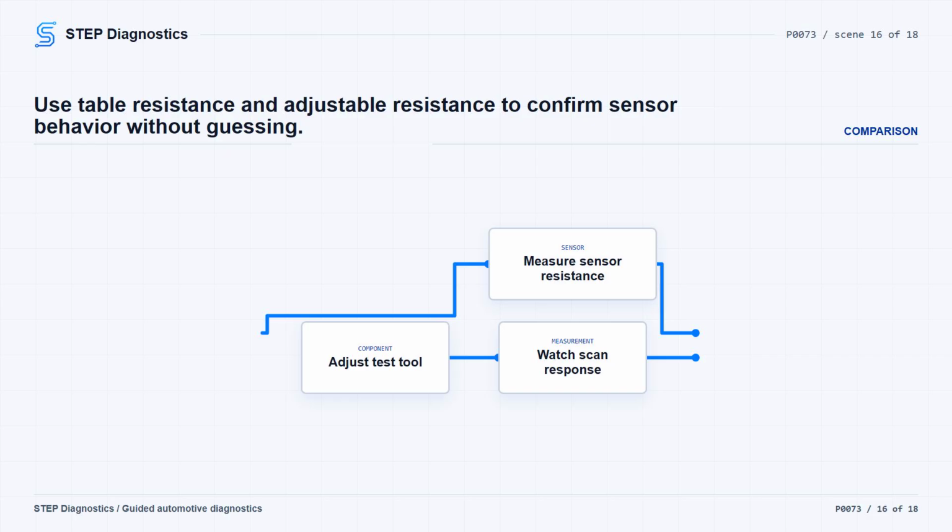Some useful points in that table are: -40 degrees C/-40 degrees F/345.26 k ohms, lowest possible temperature reading; -10 degrees C/14 degrees F/53.38 k ohms, logical temperature values; -5 degrees C/23 degrees F/40.89 k ohms; 0 degrees C/32 degrees F/31.56 k ohms; 5 degrees C/41 degrees F/24.55 k ohms; 10 degrees C/50 degrees F/19.24 k ohms; 15 degrees C/59 degrees F/15.22 k ohms; 20 degrees C/68 degrees F/12.13 k ohms;